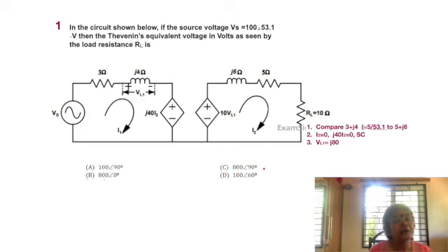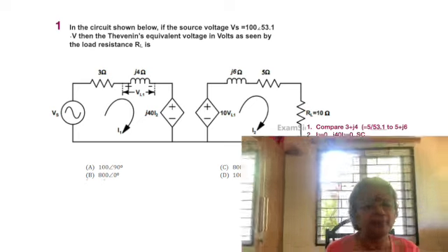That is, the impedance magnitude is going to be the square root of 3 squared plus 4 squared, which is 5, and the angle when it is 3 plus j4 is 53.1. Okay, this we can remember at any point. That's even better to remember. On the other hand, if it is 4 plus j3, the impedance remains the same, equal to 5 ohms, but the angle becomes 90 minus 53.1, that is 36.9. So this is an important concept that you can carry even to the GATE examination context. Okay, so that's one point that I wanted to make clear here.